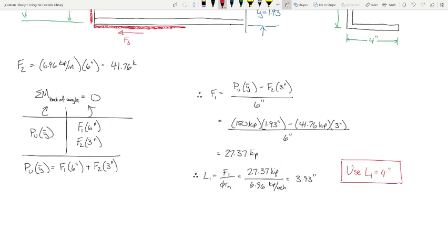That's true. Well, okay, that's a good question. I get what you're saying. I still think it's a good idea to do this from a rounding perspective, because we want to make sure that weld is long enough. This might be a downside with balanced welds, but based on rounding, we might end up getting a total of 23 inches at the end of the day. We have to make sure we supply enough weld on that back leg to resist the force necessary to keep it in equilibrium. It could end up like 21, and then we would have to add. Which is why I want to go ahead and just do the equilibrium assessment.